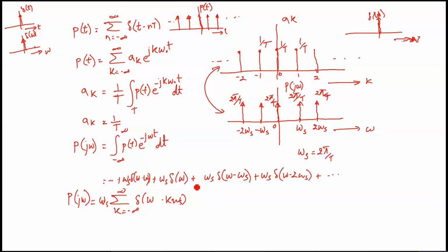So this is one way, which is kind of a novel way of finding the Fourier transform, but a very simple and easy method of finding the Fourier transform for a periodic signal. If you have a periodic signal, we can find the Fourier series, and from the Fourier series we can find the Fourier transform just by inspection and just by conversion of a_k into your Fourier transform. The other is putting it inside the formula. Now putting it inside the formula also is not that complex.